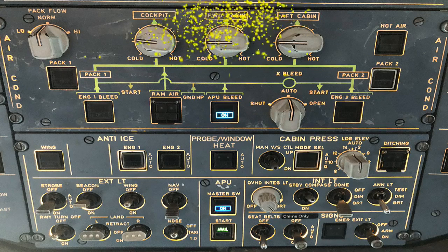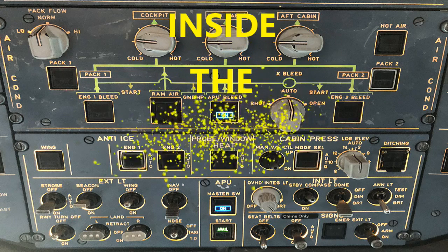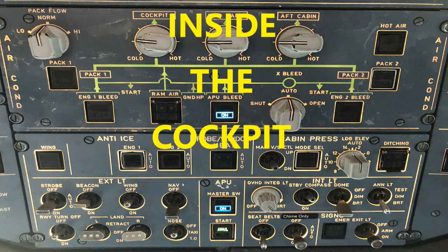Okay, at the panels. So let's look and see what kind of switches we have. I know I mentioned the engine 1 and engine 2. So what you have on there is an engine 1 bleed push button switch. You also have an engine 2 bleed push button switch. Each of those has the word fault or off. The fault will show up in an amber color. You also have a ram air button, and you also have your APU bleed. Okay, so you have those 3 buttons there.